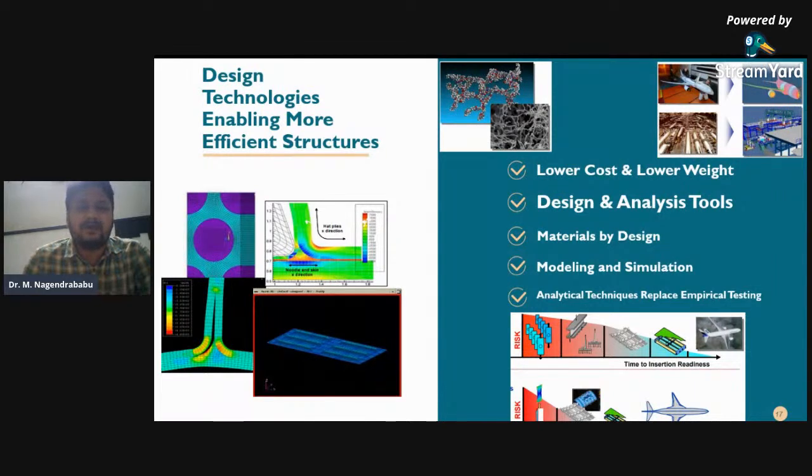Case in point, both low pressure turbine blades and high pressure compressor blades, traditionally made of dense nickel based superalloys, are now being machined from titanium aluminum based alloys. General Electric, GE, was a pioneer in this development and uses titanium aluminum low pressure turbine blades on its GEnx engine, I guess. The first large scale use of this material in a commercial jet engine in this case is the Boeing 787 Dreamliner, which I have shown you earlier.